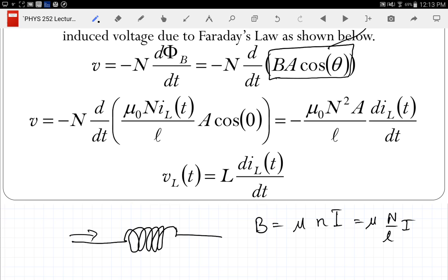Because what's going on when you put that core in the coil and it amplifies your magnetic field? What had to happen for it to amplify the magnetic field? The domains had to align. If you take something that's like this and you move it to this, that required you to do some work. So there was some energy involved, which means that you lose a little bit of energy because of that orientation change. Also, it takes some time for that to happen. And so by introducing something other than air, you introduce some energy loss.